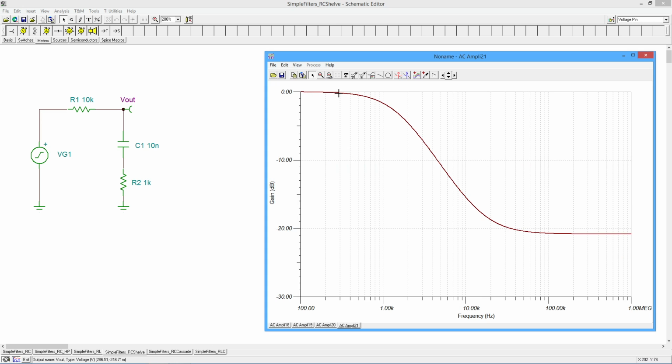But this basically starts again with this little curve, 1.59 or so kilohertz. Comes down, straightens out. But then we start to get into this area where the 1K, this R2 down here, starts to come into play. And that limits things, right? So that flattens things out instead of just continuing on down.